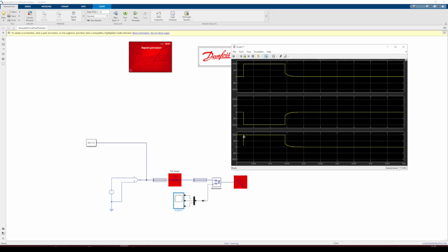The fault was initiated at the time of 2 milliseconds. So this is the instant where the fault is being generated here. We see the fault current flowing in the circuit, and since it was a 1 ohm fault impedance and 1000 volts of source voltage, the current will be around 1000 amperes here in the plus and minus conductors. And at this point, the fuse has reached the pre-arcing I2T value and will go into the arcing period and start to interrupt the current.